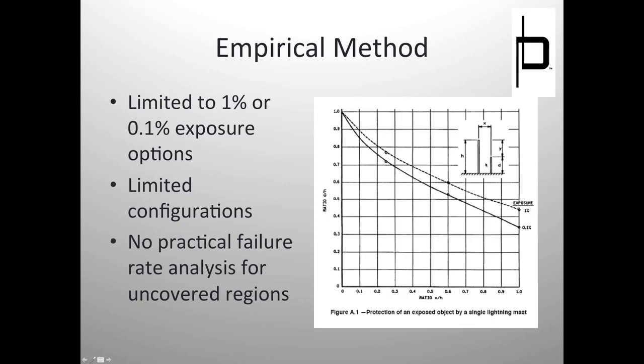Another shortcoming of this method is, what if these ratios don't apply to you? What if your equipment height is really short and you have the ability to go further? Is it safe to just extrapolate this line further? The IEEE 998 advises you not to. It says it's not, because these are all experimental numbers anyway, plotted. Now, some mathematician could come in here and figure out what the equation of this line is, and continue and draw the line out. But without real data available, the IEEE says, don't extrapolate this line beyond these ratios.